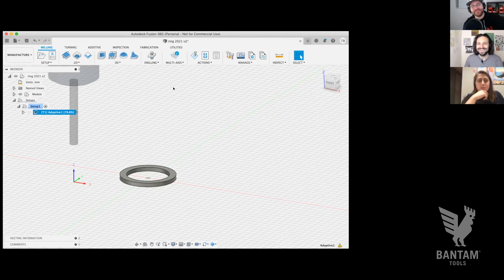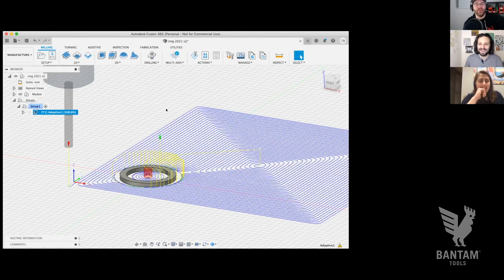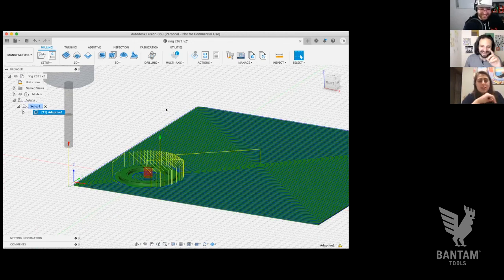There we go. This is a wildly inefficient tool path we've created. This is inefficient, but it's worth seeing, I won't lie. Can I explain what I think I'm seeing? We told it, hey, you've got a rectangle of aluminum, and what we want is just this little piece. So the program said, okay, if you want just the ring, then I will use the tool to eradicate the entirety of the rest of the block, so that only the ring remains. That's pretty much it.